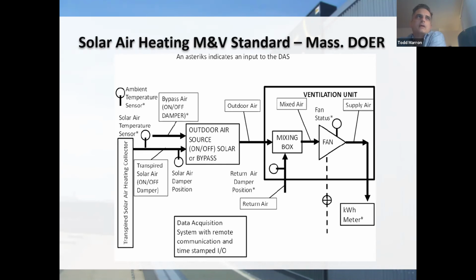So what we've done is we've sort of standardized our M&V in the sense that we try to eliminate the necessity for an actual airflow measurement, and instead we rely on a test adjustment and balance report, like a TAB report at project commissioning, to substitute for point measurement of that CFM. So you end up with a result where you can hard code the CFM value based off a TAB report, as opposed to field measurement of that airflow. So in a perfect world, we'd like to find something non-installation sensitive, something that the installer can't mess up, because we all know the installer will, and that we can use in the field to accurately measure airflow, and that would alleviate the need for us to base it off the TAB report and get at a better number.